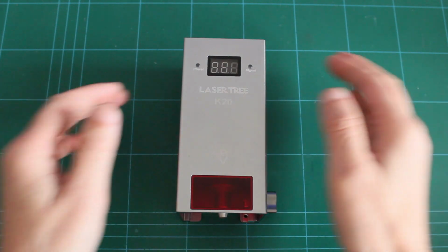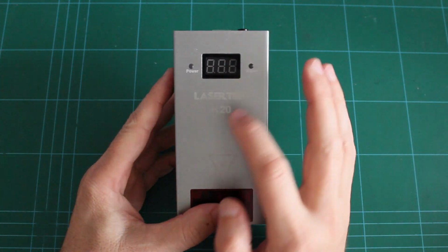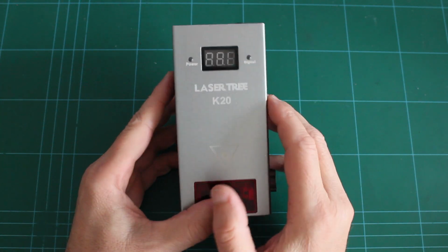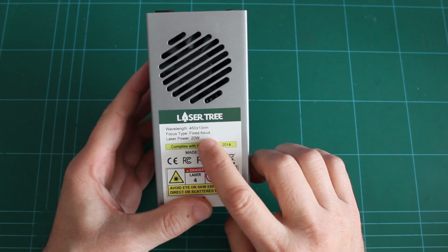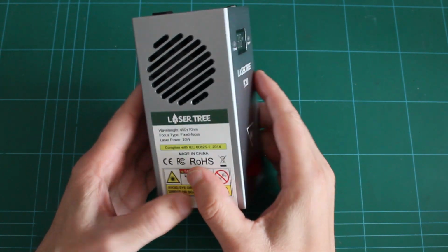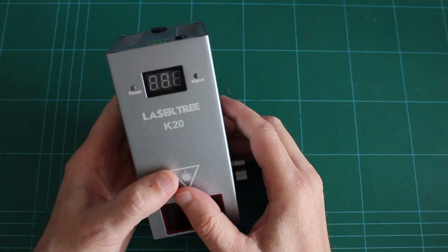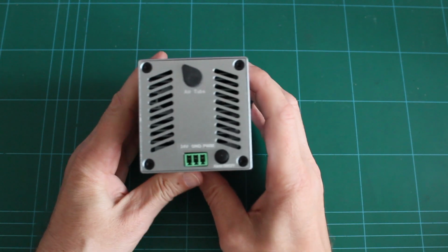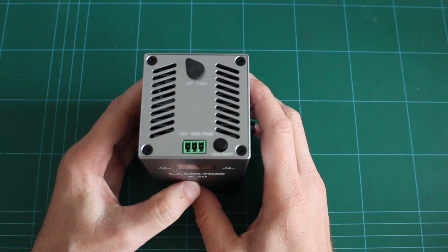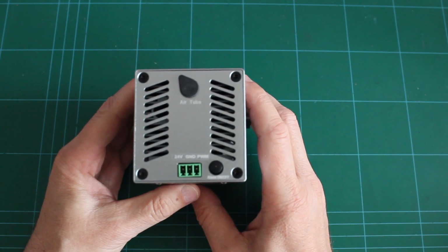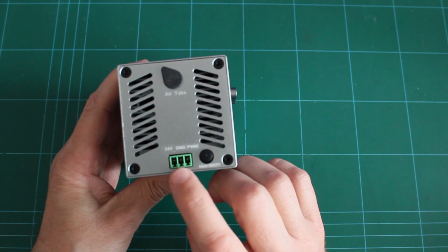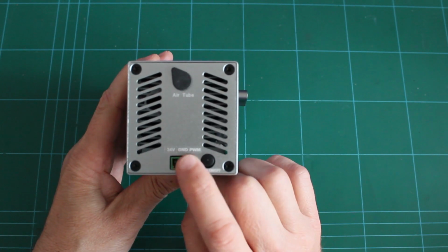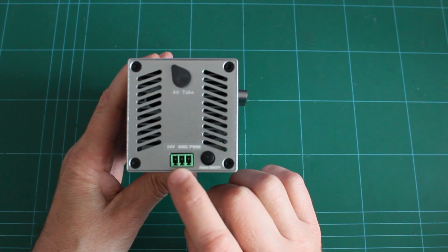In our example, we will use the 3K20 laserhead to cut the foam. It is a semiconductor laser with an optical power of 20 watts. The laser power is controlled by a PWM signal. The laser module requires a 24-volt DC power source with a minimum current of 5 amps. The control signal and power supply to the laserhead are supplied via a 3-pin detachable connector.